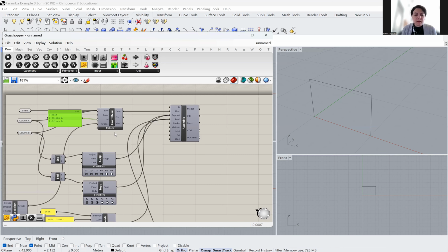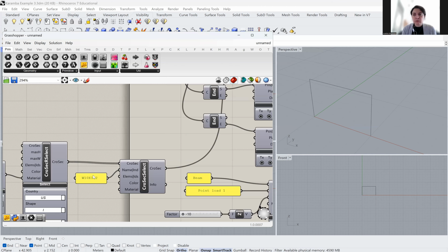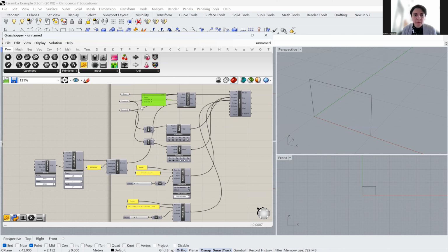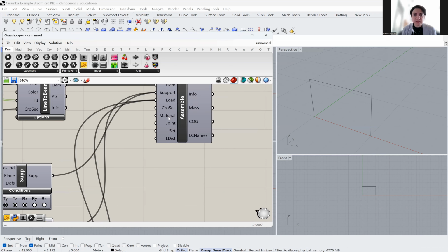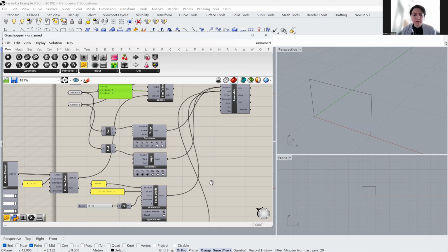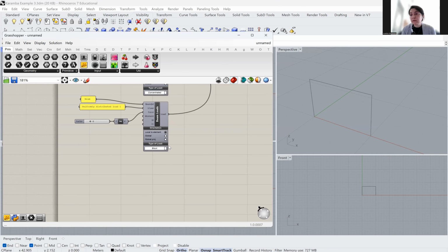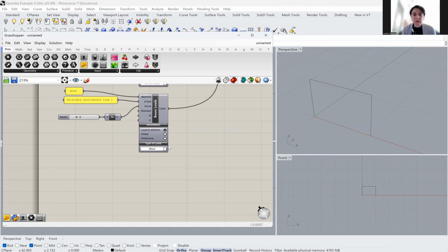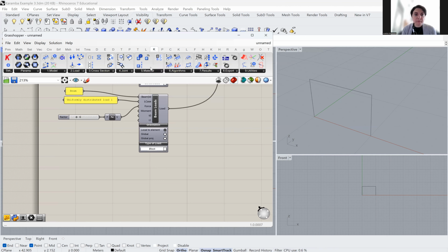Okay. The good thing here is that you don't need to convert any inches to centimeters, because you're basically just referring to the name of the US steel profiles. So we define the cross section, we define the materials and the joint. So we have a beam held by two columns. We should define how that beam is connected to those columns, and we should define the joints at that connection.